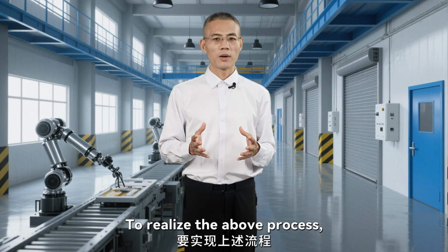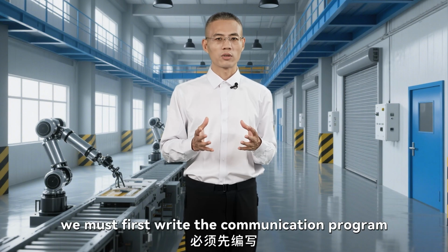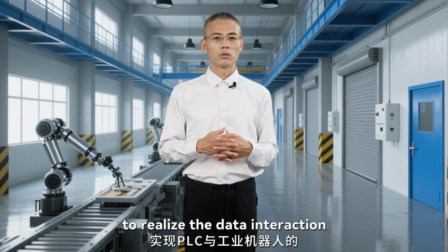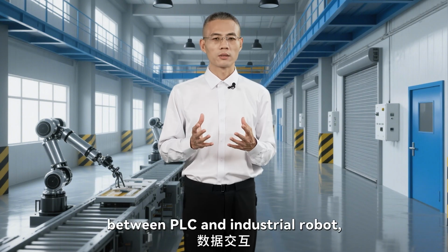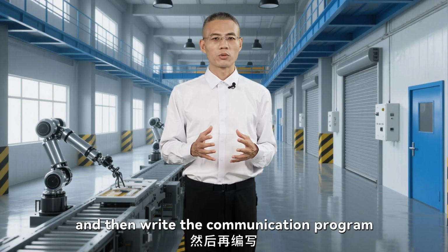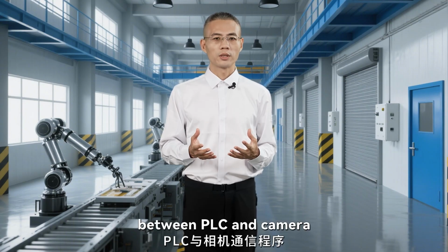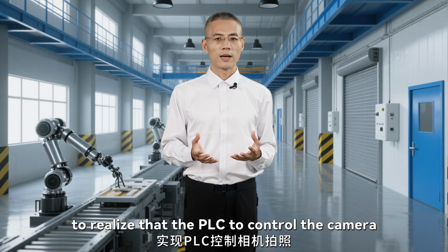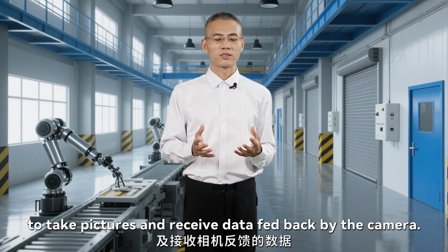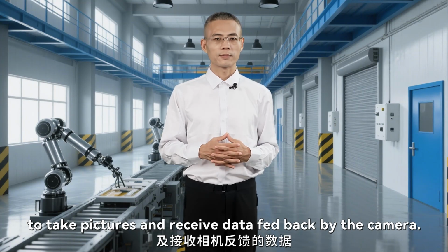To realize the above process, we must first write the communication program between the PLC and the industrial robot to realize the data interaction, and then write the communication program between the PLC and the camera, so that the PLC can control the camera to take pictures and receive data feedback from the camera.